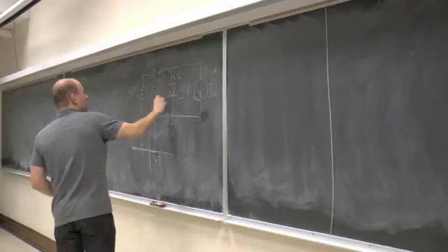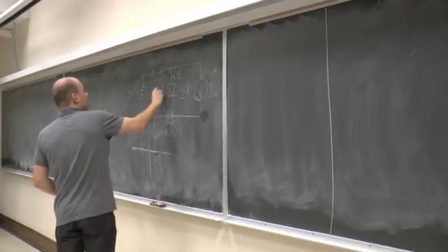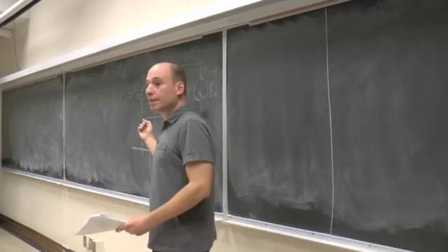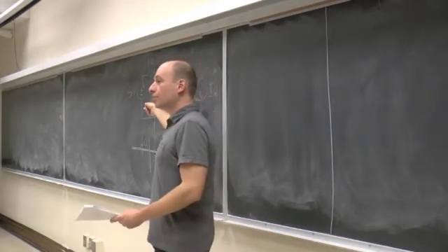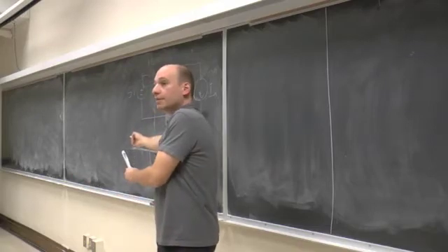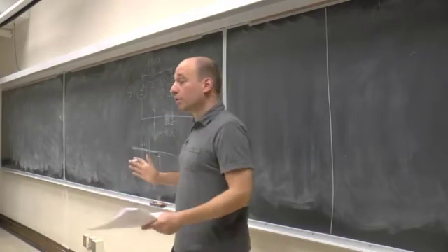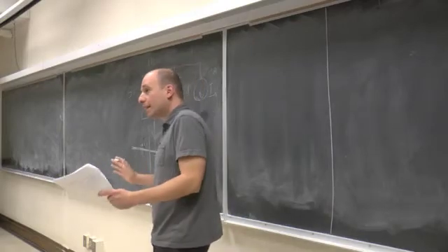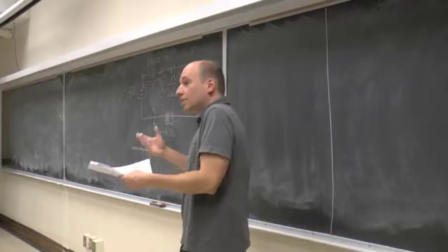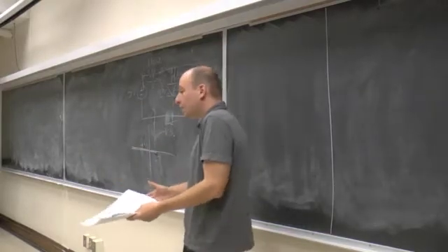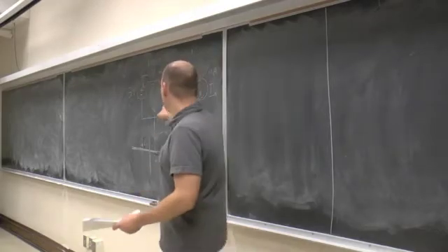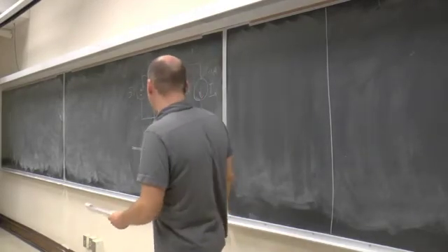We could just write 0.7 volts, without erasing the diode or rewriting the circuit, okay? This kind of on-circuit analysis will definitely take you farther. Professor Brunet is not doing, in my opinion, anything wrong at all. She's giving you a bit of a crutch, right? But if you can move past to this, that's fine.